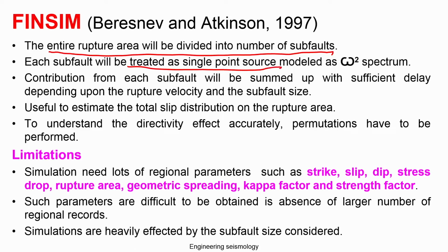So, here instead of one single point simulation by Boore, these people divide the rupture area into subfaults, and then model each segment as a point source with the omega square spectrum. The contribution from each subfault is summed up with a delay depending upon the rupture velocity and subfault size. Then finally, they arrive at the total ground motion from these small subfaults.